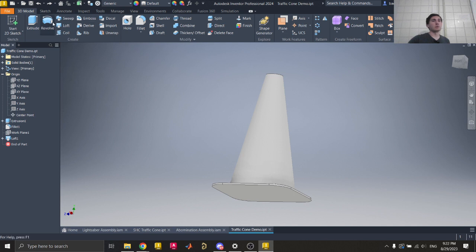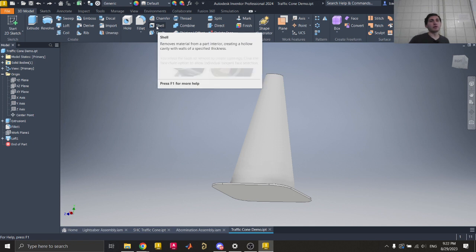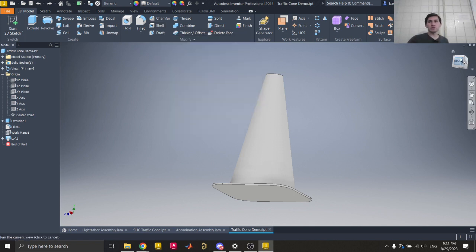We can use the revolve tool to make some sketch in the middle where we do a revolved cut, where rather than adding material, we're cutting away material. We can do something like that. We can do some fancy extrusion from the bottom where we go up and try to have it constrict at an angle. There's a bunch of different ways that we can do that, but probably the simplest one is this magic little shell tool right here. And we'll do that in just a little bit.